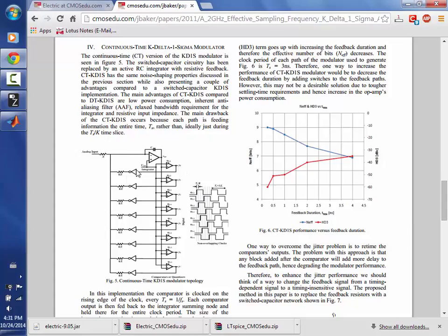The issue here, as I mentioned, is that this one switches and then provides a feedback signal for the entire slow clock period. Then the next one switches for the entire slow clock period, etc. So you basically got a whole bunch of worthless information, because after the first part of the clock cycle you're sending back, that stuff's meaningless. So you need to adjust the feedback so it's only sending back a chunk of charge. One way to do it is with a simple set reset circuit, which goes to a high Z state, and I can sketch one for you.